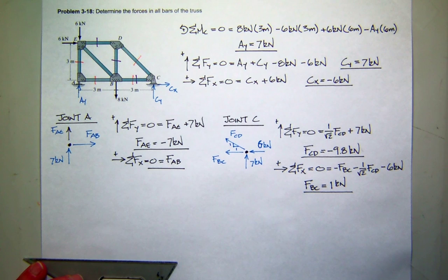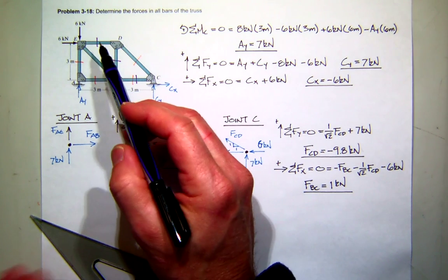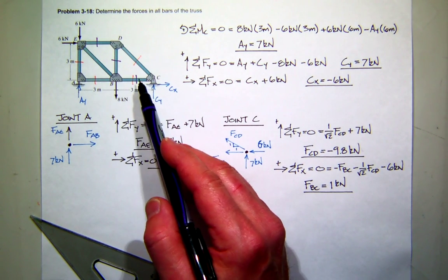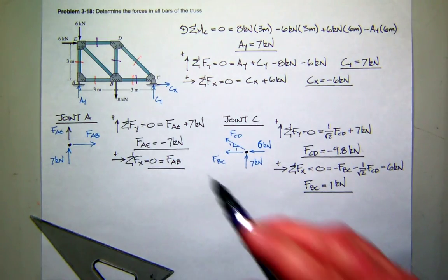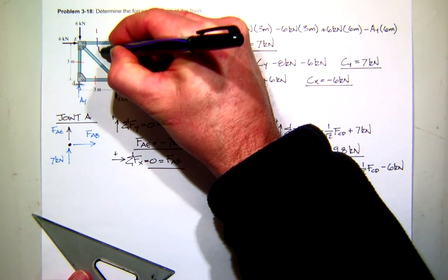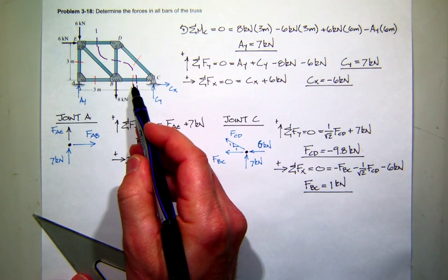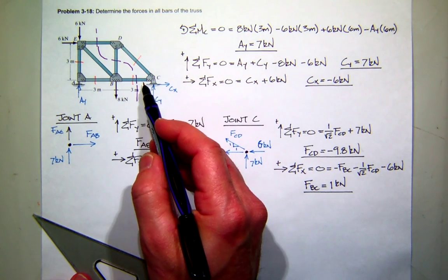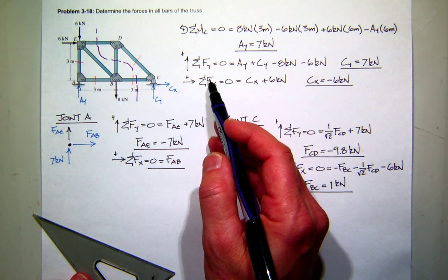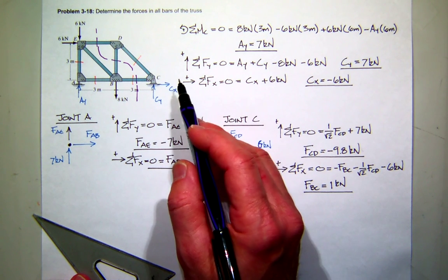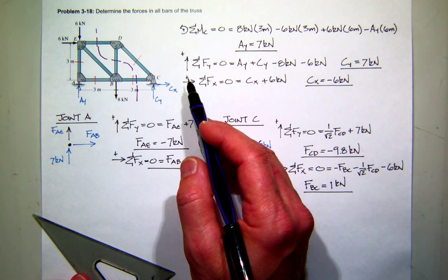Okay. Now that we've done that, which is kind of off in the wrong direction, if the original problem, as stated, was just looking for these 3 bar forces, you could cut that section and now look at a free body diagram on the left side or a free body diagram of the right side and do method of sections. You guys have a preference? I think the right side has less going on.